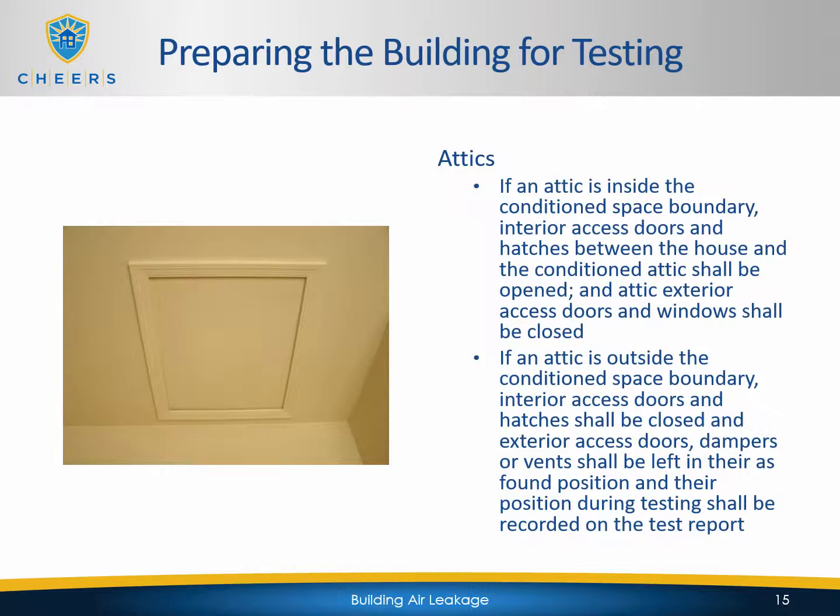If an attic is outside the conditioned space boundary, interior access doors and hatches shall be closed, and exterior access doors, dampers, or vents shall be left in their found position, and their position during testing shall be recorded on the test report.